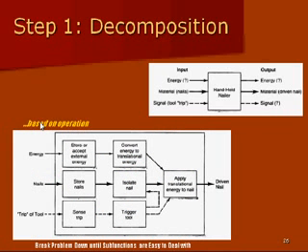What might that look like based on operations? Well, energy-wise, we could say that we need to store energy. And there may be many ways to do that. Then we're going to convert that energy, whatever form it's in, into a physical translational energy that's going to be applied to the nail and lead to the driven nail. So that's the flow of energy along the top here. If we look at the flow of nails, we can say that the nails are going to be stored, and then a single nail needs to be isolated from the group of nails. And that single nail then is going to have energy applied to it, and that's going to be our driven nail.